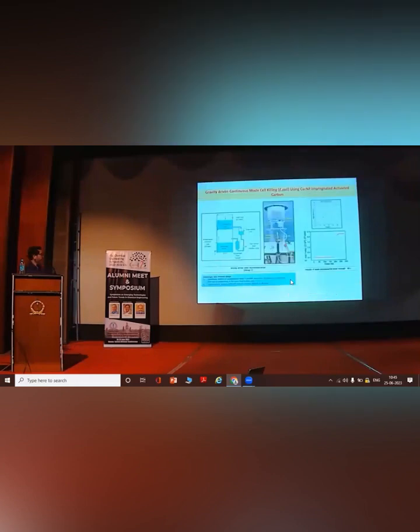And we are now testing a 20-liter system in the lab where you can store 20 liters of contaminated water. It enters through this filter column, driven by gravity, flows upwards, there's good contact time. So what comes out is collected in this jar. And we are doing the breakthrough curve analysis and all that. So the idea is enhancing the throughput, without power, a gravity-driven system.